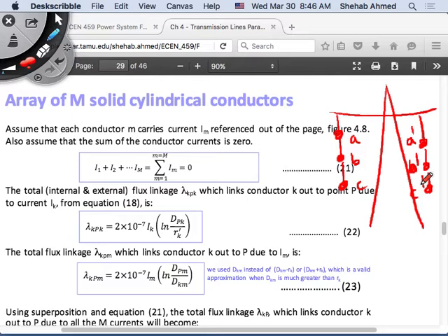These are threats that we see or hear about these days. Even though it's crazy stuff, it still happens in the world, so power engineers have to deal with it and make sure to build a redundant system. So double circuits are nice, and the tower footing or tower space is one. I don't have to have space for two towers, which is more painful, with more land cost, visual impact, and roads leading to these towers. All of that is reduced if I use a tower with double circuits.